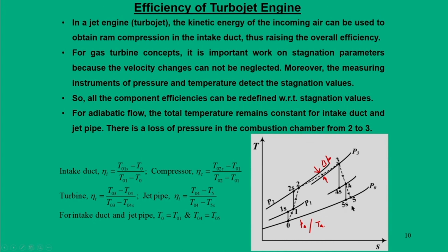Now, here are the typical conditions when this expansion takes place. Whatever type of nozzle people use in the engines, typically the nozzle becomes choked. That means that is the optimum flow rate or optimum thrust that can be achieved from the nozzles. So, normally conditions 5 and 5s are almost above the ambient value, and the flow condition is typically choked, and in fact the pipe and atmospheric pressures are not equal. So, the entire calculation is governed through the choking condition of the nozzle.